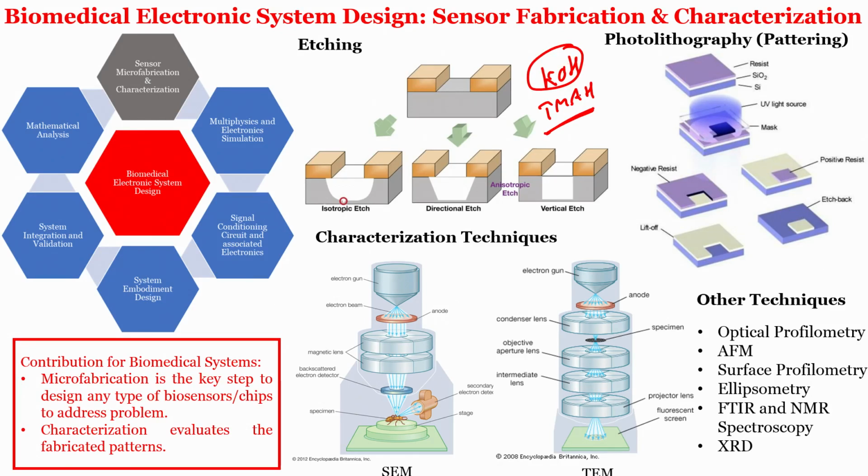In KOH the walls that you see are rough. In TMAH the wall, this wall, right, is smoother. TMAH is neurotoxic, KOH is not. But everything should be used in a wet bench environment with a proper exhaust. So, again, why are we learning lithography? Because we want to understand how the patterns are formed. Why are we learning etching? Because finally the sensor is fabricated, right.